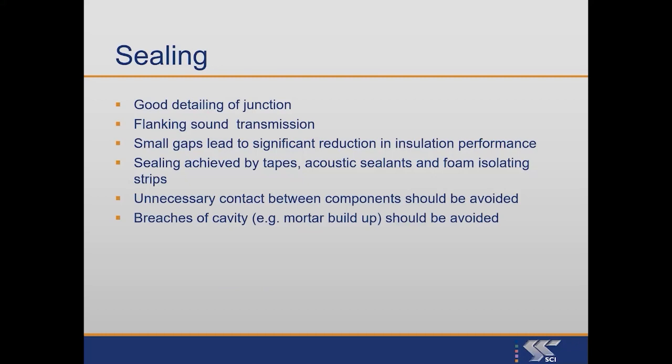You also want to make sure that you've got good sort of construction practice. Something that's caused poor acoustics in the past is a build-up of mortar on wall ties between leaves of masonry. So if you get lots of mortar build-up on the wall ties there, or the brick ties, then that reduces the amount of sound insulation that you can get between two leaves of masonry in that case.